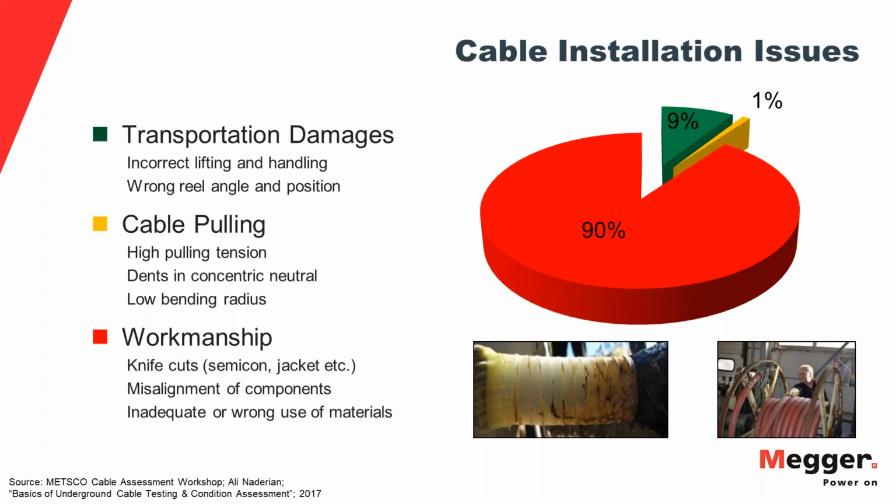So there is even a strongly preferred way of storing the drums before you go out, before you go into the trenches to pull the cables. If you store the drums the wrong way in your yard, then you're setting yourself up for failure. Another thing: when you store the drums, I can only appeal to you, always put end caps on.